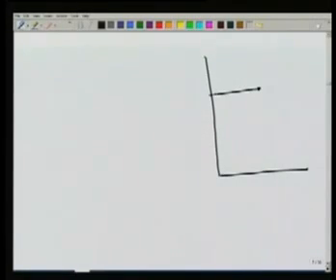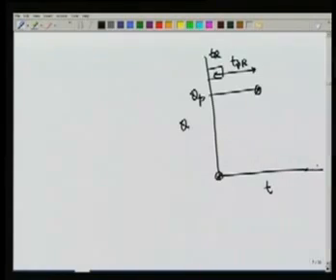This is QP, TR, and TPR. So we have 1 point here. Here we know it will start at 0, 0. The other information which we have is that the area under the curve should be equal to 1 centimeter of depth over the catchment area.